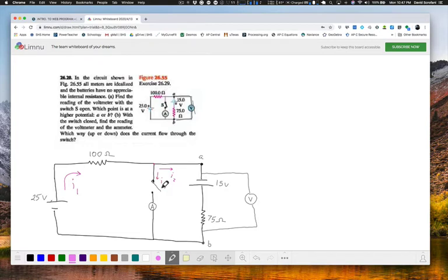And the answer to that question is resoundingly no, because this switch is open, so there is no I3, and that means by continuity at this point right here, I1 just flows right across that junction. It's really not a junction. It just continues right on over here, and so really there is just I flowing around this entire circuit right there.